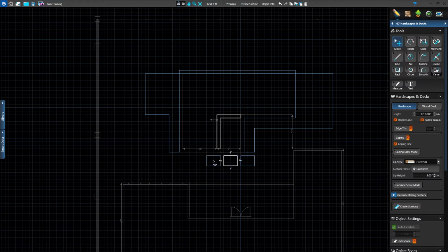We'll use this technique to add 5 pavers in front of the pool. Once the pavers are in place, we'll select the 5 pavers to create another row. Hold down Control and click each paver to select it. When a shape is selected, it will highlight in white.